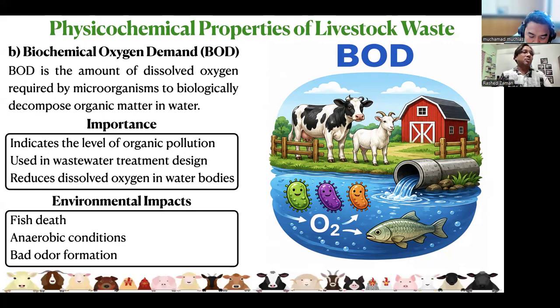Importance of biochemical oxygen demand. It indicates the level of organic pollution, because higher BOD means more organic pollutants are present in the wastewater. It is used in wastewater treatment design, because BOD helps to determine how much treatment is needed to remove the organic pollutants.